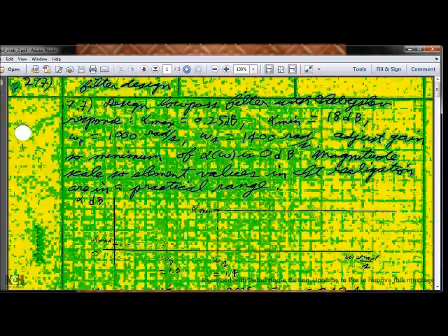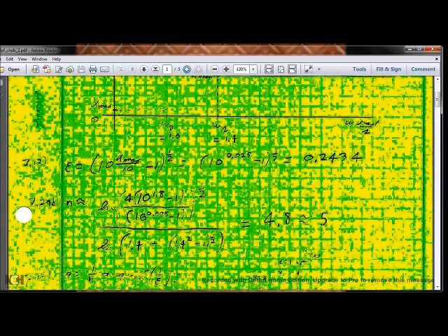Pass band edge is 1000 radians per second, omega p. Omega s, the stop band edge, is at 1400 radians per second. And we'll scale the magnitude so element values in the circuit are in a practical range.